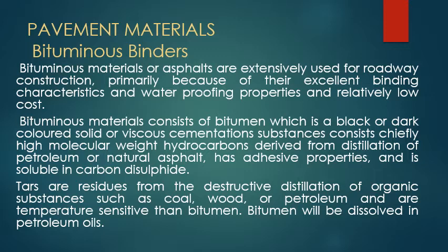Here and there, we have seen from our childhood days the construction of these bituminous roads. Mostly this binding material is used for the wearing course construction. Apart from that, have you seen this bitumen being used in other layers? Yes, definitely. It is used in the lower layers also, but not to the quantity that we use for the wearing course. The percentage is relatively higher for the wearing course, where it is mixed with the aggregates at a larger percentage.